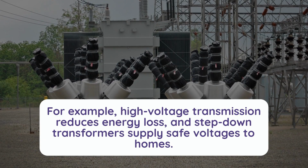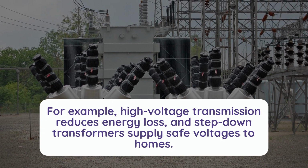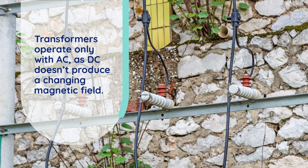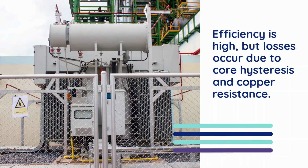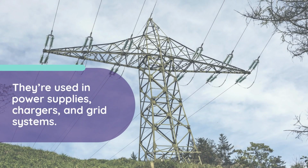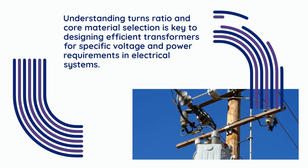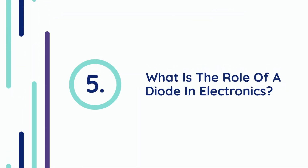For example, high-voltage transmission reduces energy loss, and step-down transformers supply safe voltages to homes. Transformers operate only with AC, as DC doesn't produce a changing magnetic field. Efficiency is high, but losses occur due to core hysteresis and copper resistance. They're used in power supplies, chargers, and grid systems. Understanding turns ratio and core material selection is key to designing efficient transformers for specific voltage and power requirements in electrical systems. 5. What is the role of a diode in electronics?